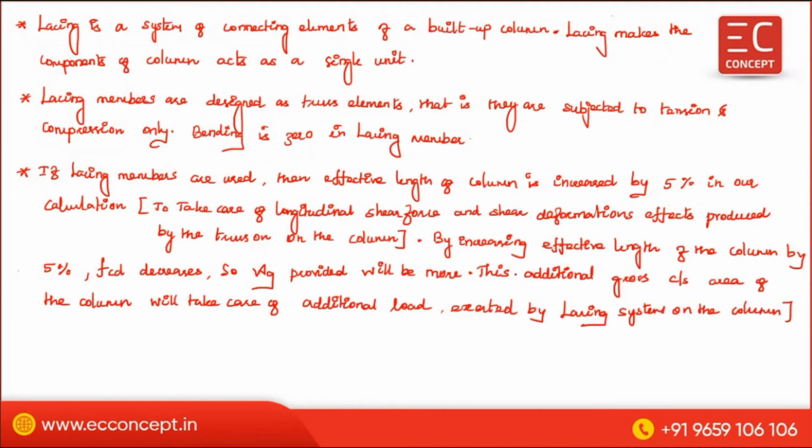Once you increase the effective length, automatically the design compressive stress reduces. If it reduces, then the cross section area will be increased, and that will take care of the additional load exerted by the lacing system.